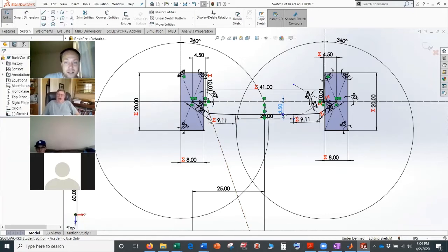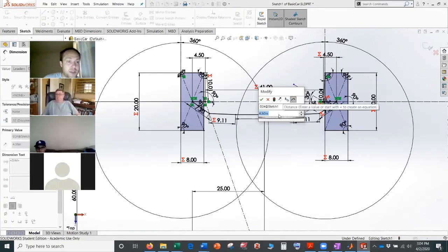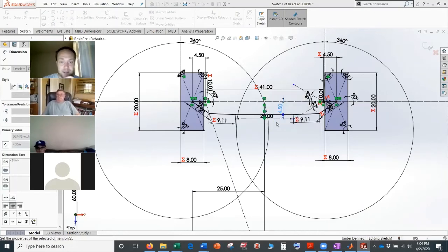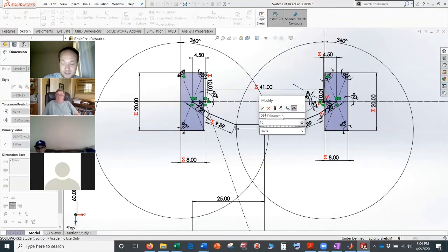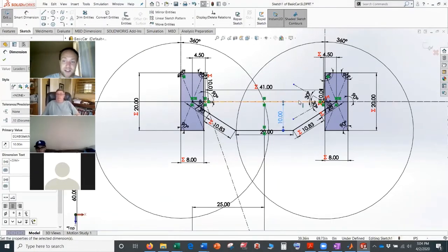So for example, the reason why we could turn more in that last case, if I go to like 8, let's go to 10. You'll see in this case, this is like a bad position for my rack, right? Because in this case, my tie rod is already going over center with the steering arm. And I haven't even moved it. So like this setup, you can't even turn your tires. It's just a bad setup, right?